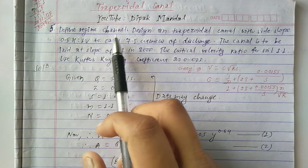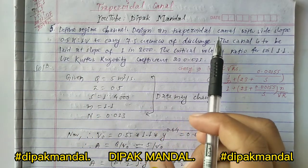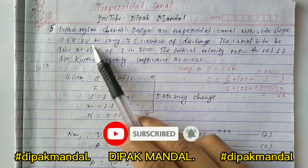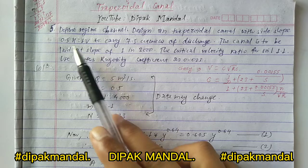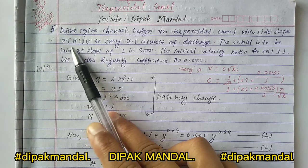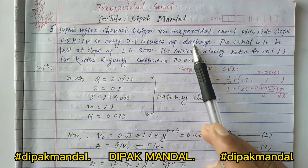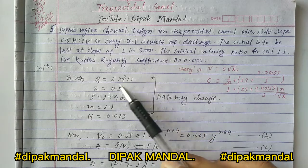Okay, define regime channel. This is the definition part. And design a trapezoidal canal with a side slope 0.5 H is to 1 V. We have been given the side slope 0.5 is to 1, in horizontal 0.5 and in vertical 1. To carry 7.5 cumecs of discharge, and the discharge is given over here 5 cumecs, and you can say 5 meter cube per second.